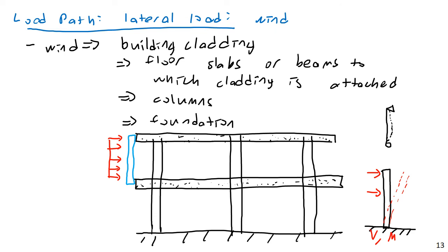They not only have to support the vertical loads, so we can see here one of the reasons that column design is so tricky and so critical. Columns need to carry quite a bit of different types of loading. They'll always have to carry vertical load from the distributed vertical loads of dead load, live load, self-weight, etc. They'll always have those big vertical dead loads, but they'll also often have to carry lateral loads from wind, from seismic, etc. So column design is always very critical and very tricky because of this.